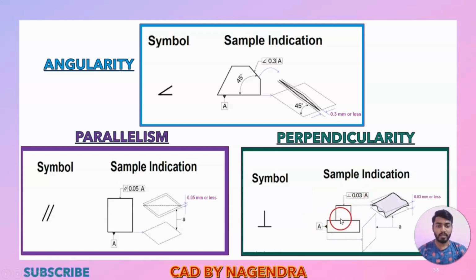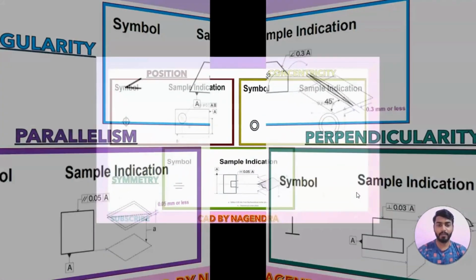It means normally if you design this part, if you give specification for this production, we will not have any proper relation between this line and this line. So there we will mention this shape. If I maintain perpendicular here, properly this line should be horizontal, properly this line should be vertical. If you are not maintaining this, maybe he can manufacture this with parallel relations. So here we are able to see the form and shape of the profile.